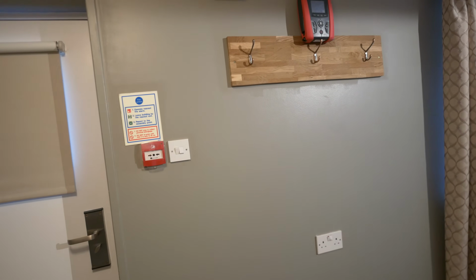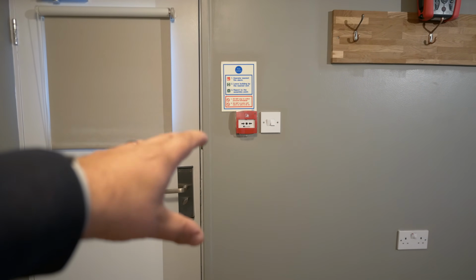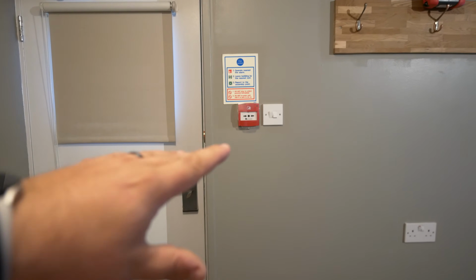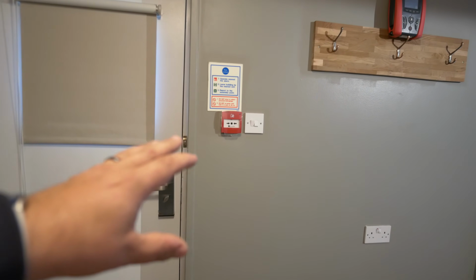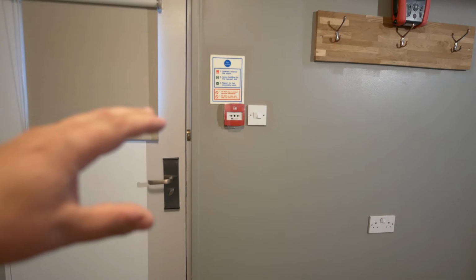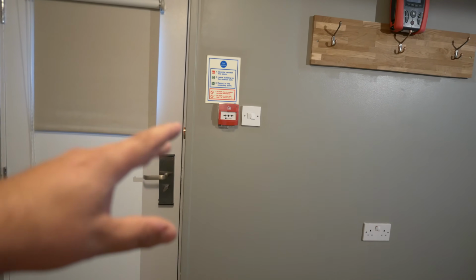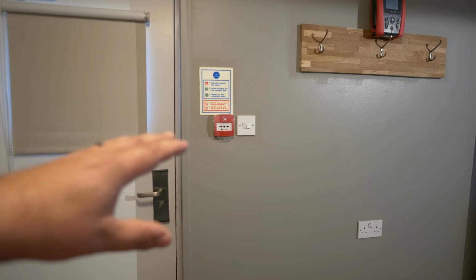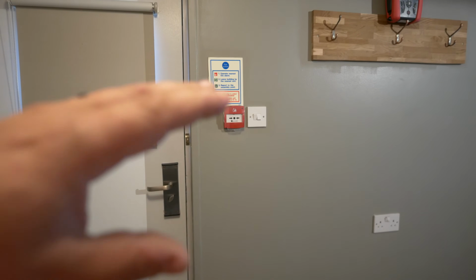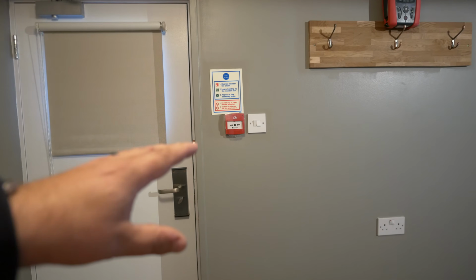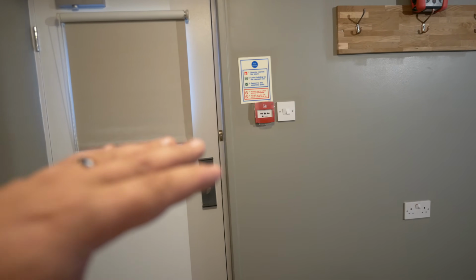a radial lighting circuit. Now there is also a fire detection system in here that will most likely be supplied from elsewhere, and we need to make sure we note that in the limitations of our inspection, that it's not forming part of our report. Fire alarms are mentioned in BS 7671, and although there is a separate British Standard for that particular type of equipment and installation, it's well worth making sure you cover that off in your limitations, or the outset of what the EICR is covering, that is excluded. We're not going to be covering that in this aspect of our report.